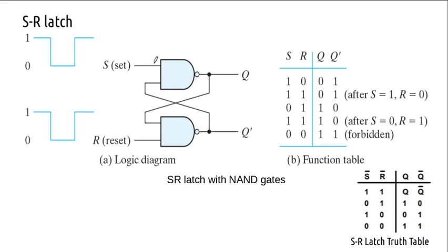The NAND gate is what we mostly use for explanation, so it is better to study the NAND gate explanation. He'll use a bubble to explain that. And 0 1 means it is set, then 1 0 means it is reset, and 0 0 is a forbidden condition. It's a not allowed condition. Why it is not allowed, we'll say in a while, right?